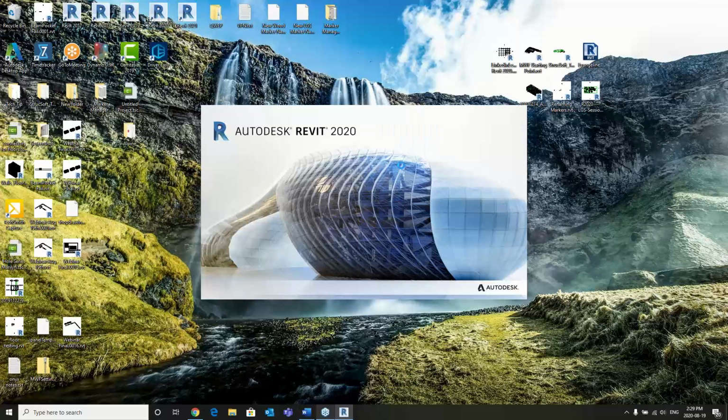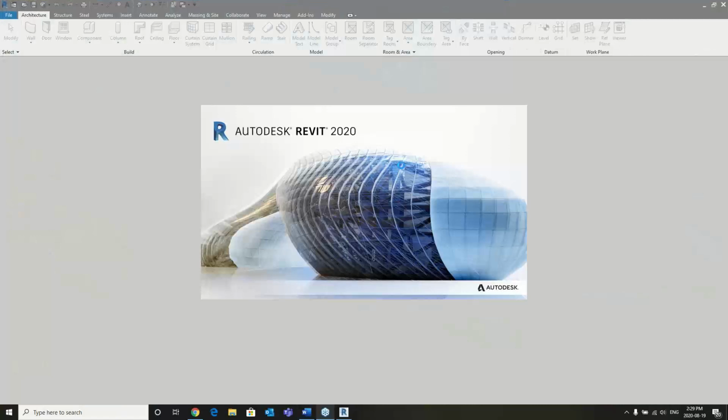All right, so typically, like I said, what would have happened is the hole would be right in the middle of the blocking, and there was another option, if you guys noticed, that said flip. Basically, that allows us to flip the hard side of the blocking with the open face. So it's a quick way of just shifting your blocking the way that you would like it.